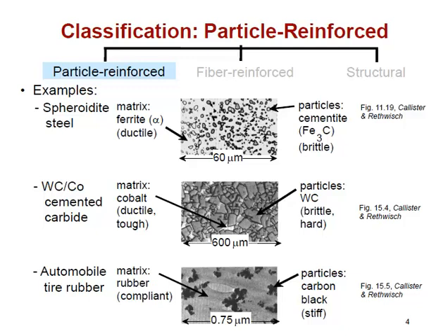And so in this case, the cobalt is the continuous phase, and it's shown in the very small bits of light color, and the tungsten carbide is the sort of the blocky phase. And in both of these cases, what you're looking at is an optical cross-section, a polished cross-section of the microstructure, very similar to what you saw on the phase diagrams, microstructural schematics.